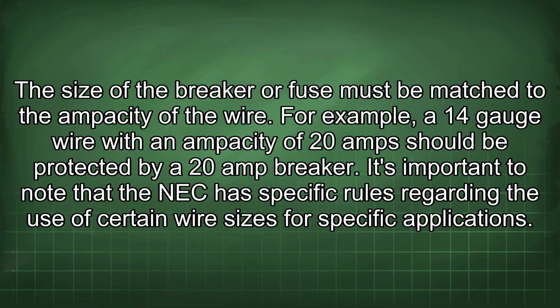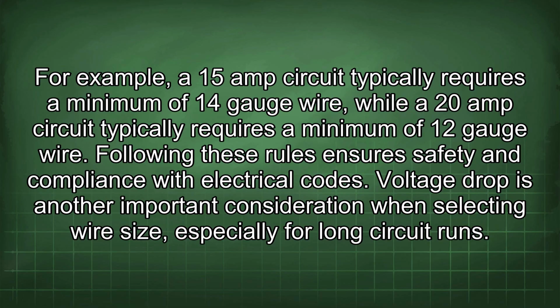It's important to note that the NEC has specific rules regarding the use of certain wire sizes for specific applications. For example, a 15 amp circuit typically requires a minimum of 14 gauge wire, while a 20 amp circuit typically requires a minimum of 12 gauge wire. Following these rules ensures safety and compliance with electrical codes.